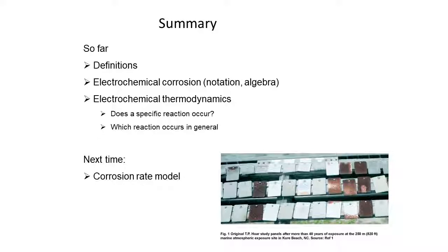So that's going to be an important part of this course because, as I said, when you have your zinc coatings, often you just need to make sure you design your zinc coating thick enough to allow active corrosion to happen for the service lifetime. And we will look at equations to make sure we're able to make sensible estimates of what thickness is needed for such metals. We'll look at that next time, so we'll see that in the future.